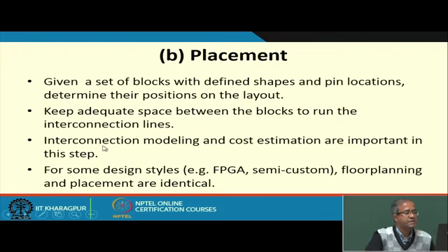So, here your interconnection modeling and cost estimation are important, because you see the exact interconnection you will be doing later during routing, but now you are trying to keep some space and place the blocks in an optimum way such that your expected cost is minimized. So, you have to use some simple estimation of routing cost, so that you can evaluate and compare between two alternate placement solutions. You can say that, well, this is more expensive than the other, so you take this.